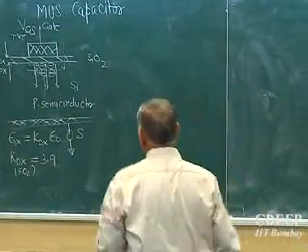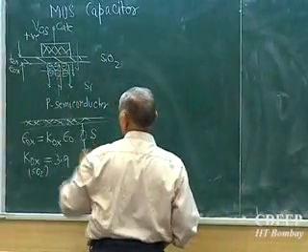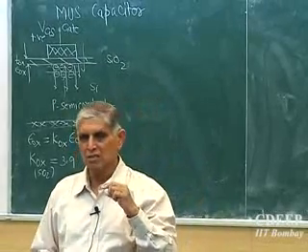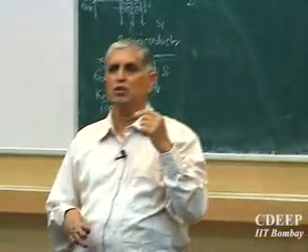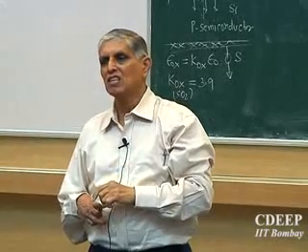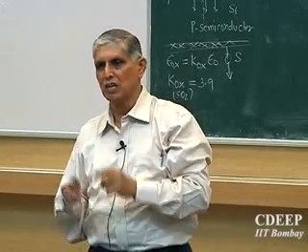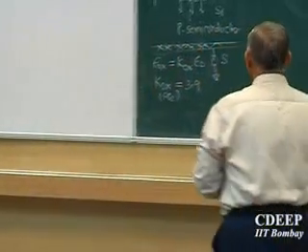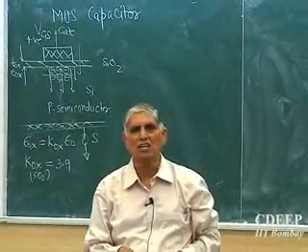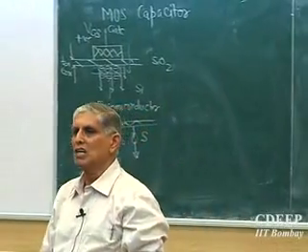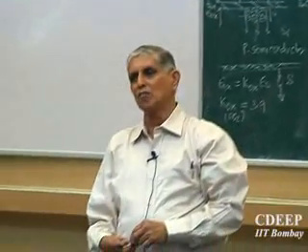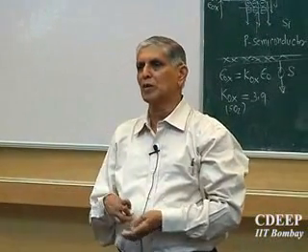However, as I increase the depletion layer thickness or width, as we call it, the electric field across this region also starts increasing, and at some value of positive VGS, it may happen that this depletion layer has a sufficiently large electric field. I will define how much now. At that time, I figure out that in normal semiconductors, as in the depletion layer, electrons and holes are constantly thermally generated. And since they are generated, there will equally be recombination. So stability has to be achieved, equilibrium has to be achieved.